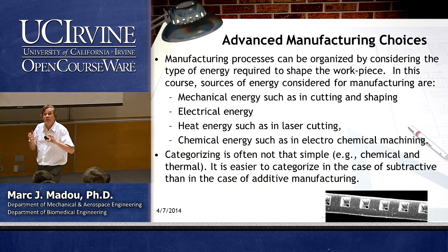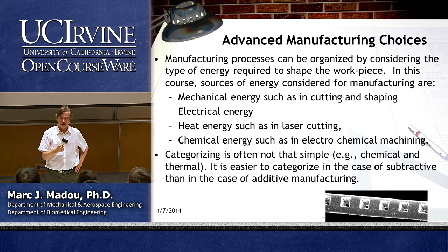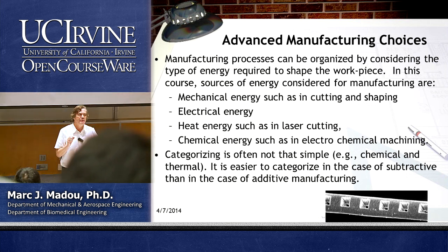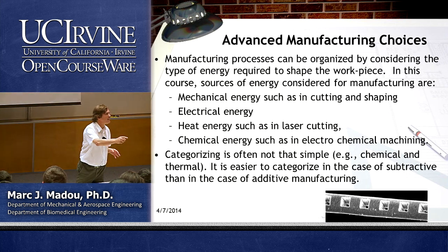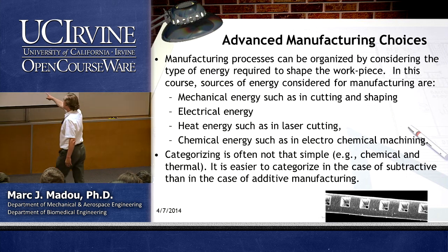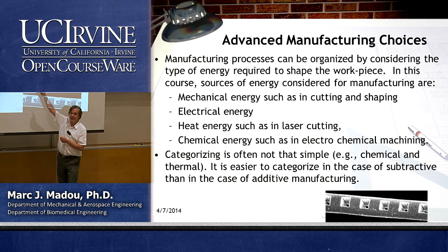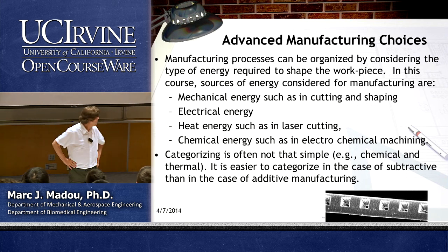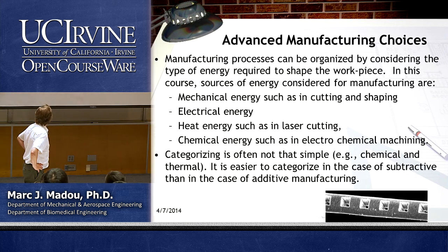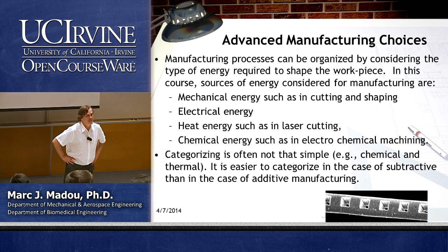And so, to give you already a little bit of a feel for things, if you do make something mechanically, let's say drilling, a good rule of thumb is this: 100 microns is about the smallest drill you'll be able to use. So if you have an object that you need to make with grooves in it, and it's say 15 microns, or it's like this, I promise you this is not made with a mechanical drill. It's one of the other techniques. We're going to learn what techniques that would be, how you could make holes of that kind of precision in a human hair.